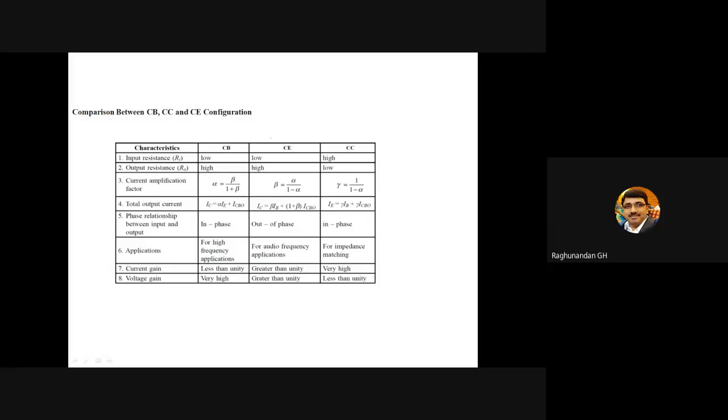Conductance increases. So when conductance increases, automatically the input resistance will be low. See, no need of by-hearting anything. Just analysis is important in electronics. In common emitter configuration, again here also it will be low,